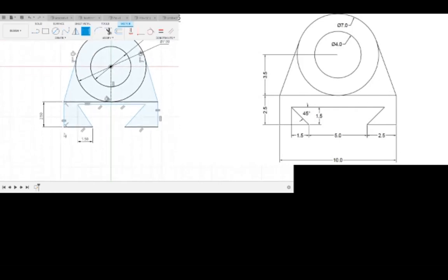We also need to set that this is in fact 10 millimeters, because these lines here are blue because we can do this, which is what you don't want. So we'll set that to be 10 millimeters, and that would be nice and constrained. The same thing can be done on the opposite side, such that these lines are equal. You can make these two lines equal, and now these lines are equal by geometric relationship. Or they're not equal yet, but they're about to be. So we set these to be equal. Now these are fully constrained.